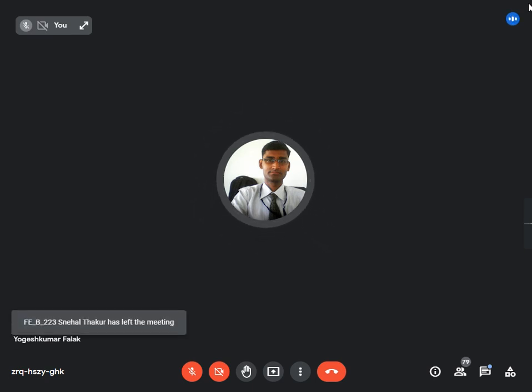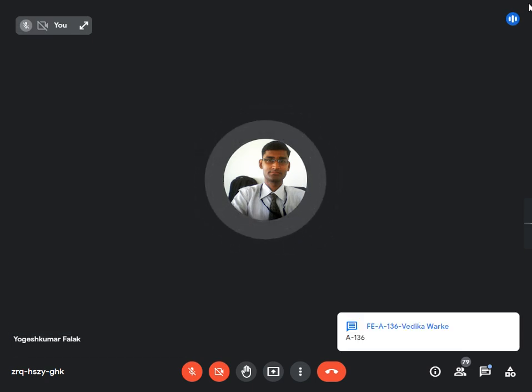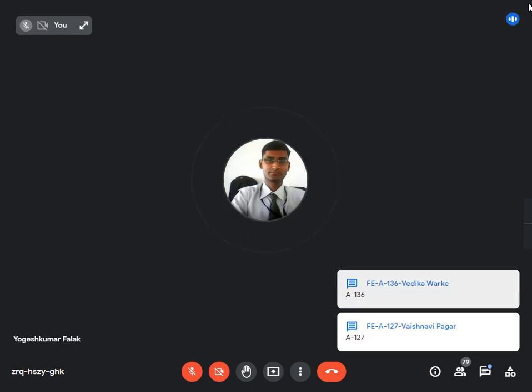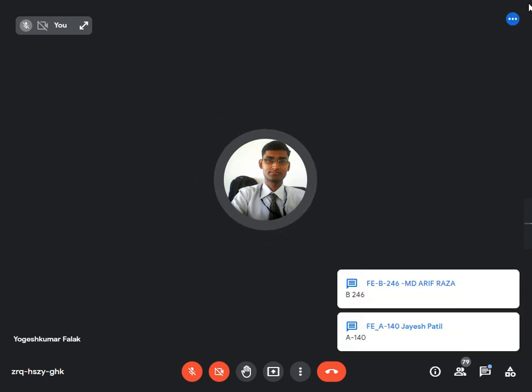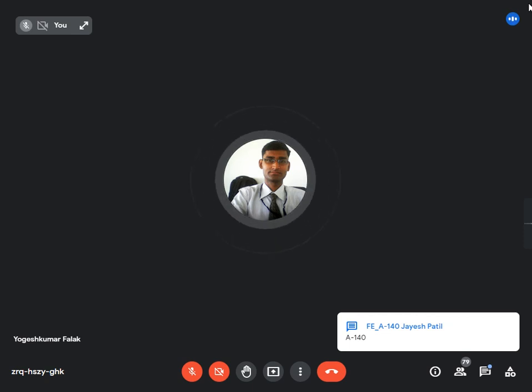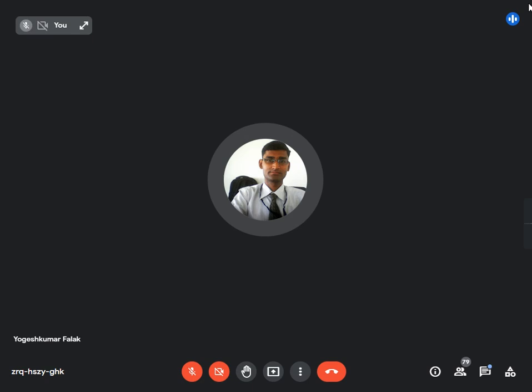The equipment is a refrigerator, and the food compartment is maintained at a very low temperature, so that is the value of Q2, right? So it is given that COP is equal to 1.5 and Q2 is equal to 360 kilojoule per minute. From these two values, you need to find out the power consumed by the refrigerator and the amount of heat rejected to the surrounding, that is the value of Q1.